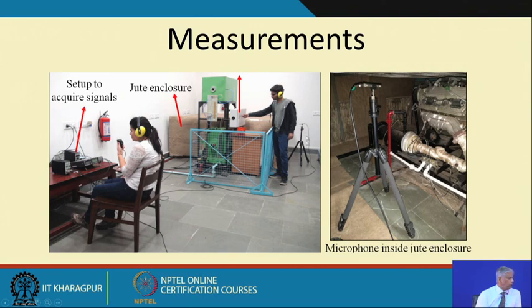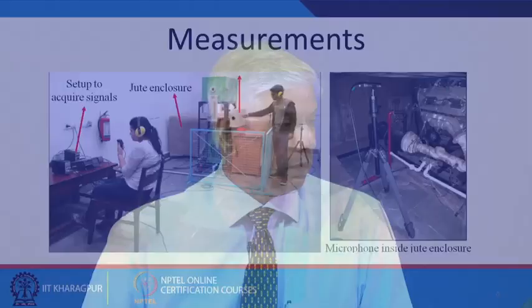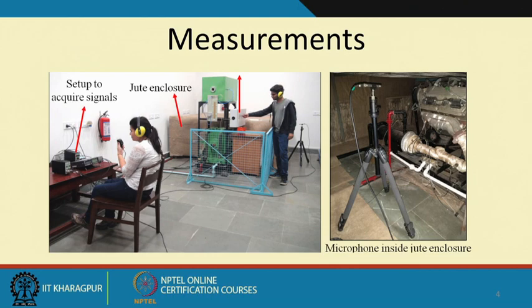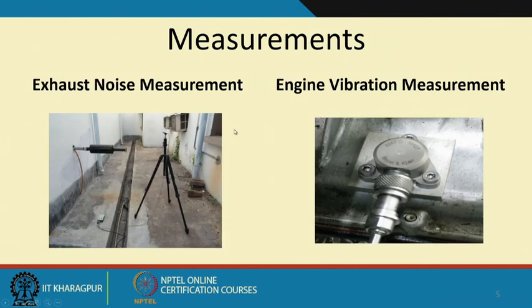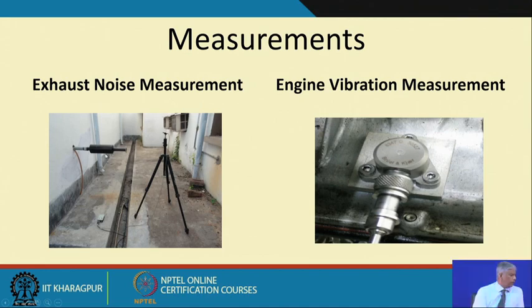We are recording all the signals coming out of this engine onto a tape recorder for subsequent analysis and to find out the characteristic qualities of the signals when a defect has occurred. And we could artificially induce defects by switching the engine on and off. And at the exhaust side, we have a muffler, and we have put a microphone here to measure the exhaust noise.